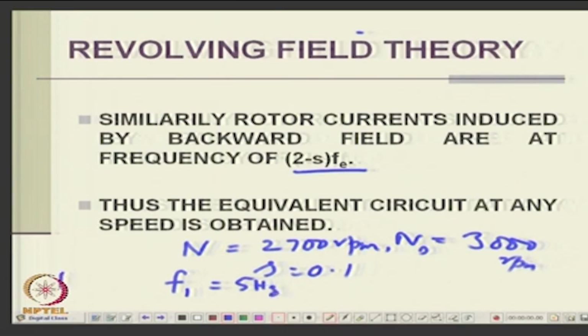Due to the backward field, how much? 2 minus S, 95 hertz. So, you will know that for the backward field very high frequency currents are induced, almost double the mains frequency. So, you can imagine it will have much higher inductances, and so on.